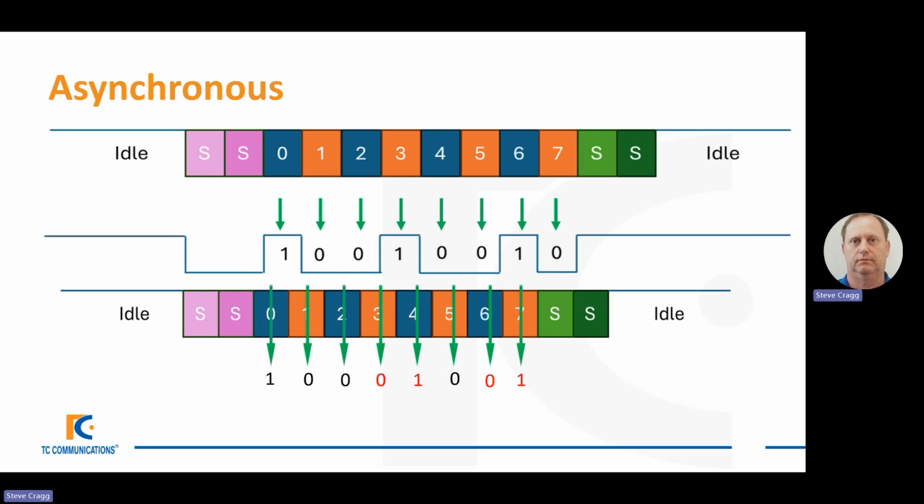And although this is an extreme example, this is probably showing around 10% slippage. What we can say is, if it was 1% and you sent a string of 50 bytes, all in a row, without the idle tone, without the start and the stop bits, it's almost certain that you would see this effect over that amount of time. So it's really important that you do send that.